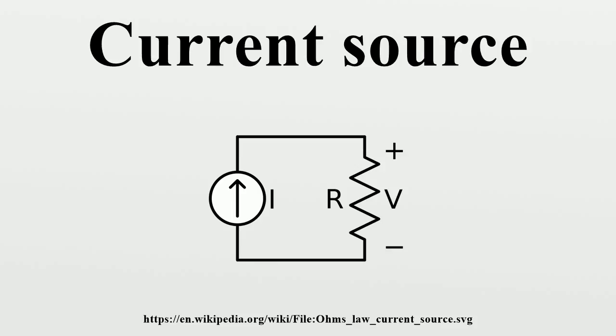If the input voltage varies, this arrangement will act as a voltage-to-current converter. It can be thought of as a reverse current-to-voltage converter. The resistance R determines the transfer ratio. Current sources implemented as circuits with series negative feedback have the disadvantage that the voltage drop across the current sensing resistor decreases the maximal voltage across the load.